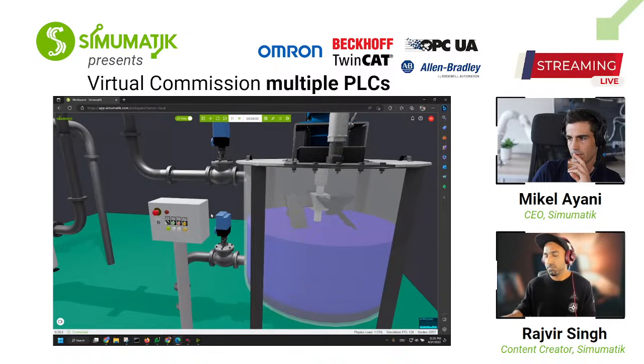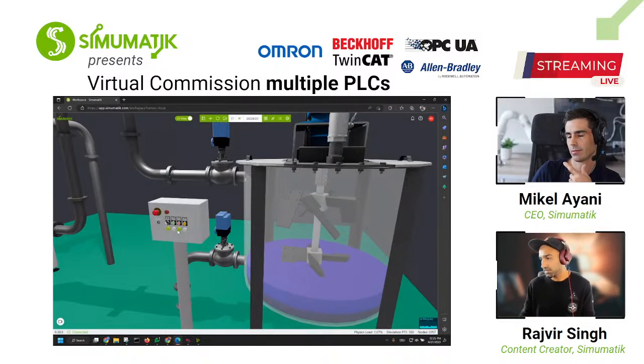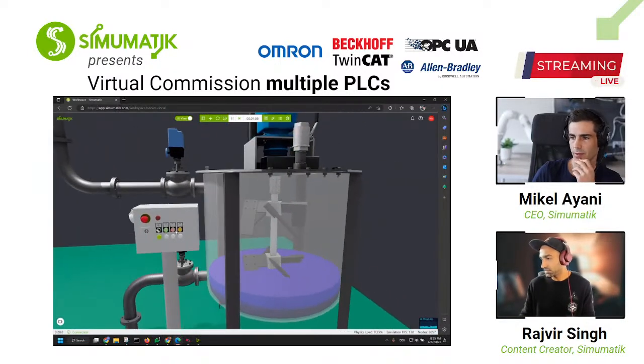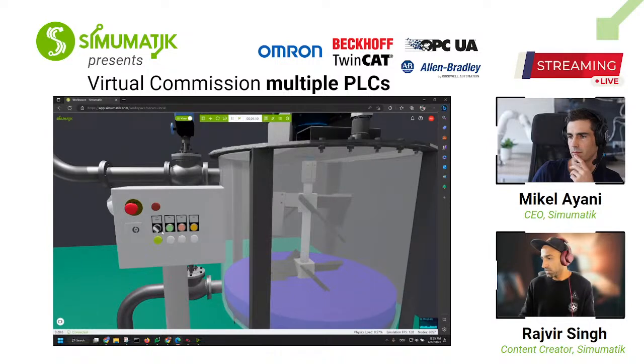And after 5 seconds of mixing, it will drain out. And then you have a draining indicator as well. And then it waits 5 seconds, and it's then doing the loop or the sequence again. You can also program the PLC in a way that you can stop it wherever you want, or start again, or press E-stop. Then you have a red light, release it, reset the E-stop, and then start again.